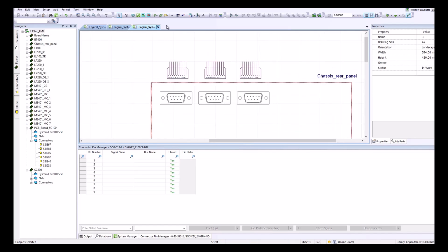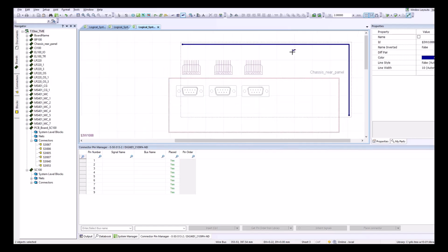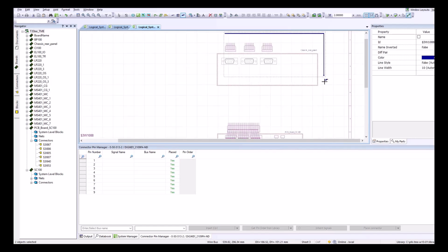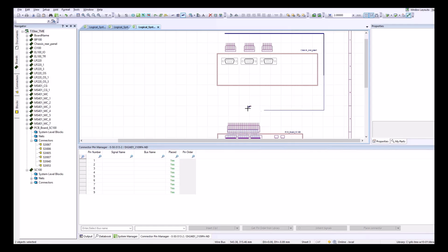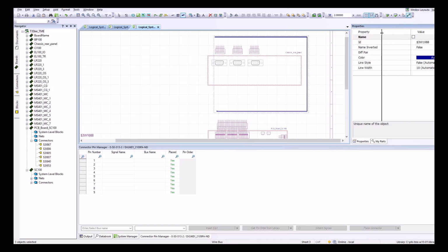So we'll go ahead and use the wire bus for this process in order to simplify the graphics and minimize the number of individual wires in the schematic. The wire bus corresponds with multiple wires, and the name of this wire bus can be generic. If required, the bus name can also be cable assembly specific. For instance, you can name it a multi-core part number.